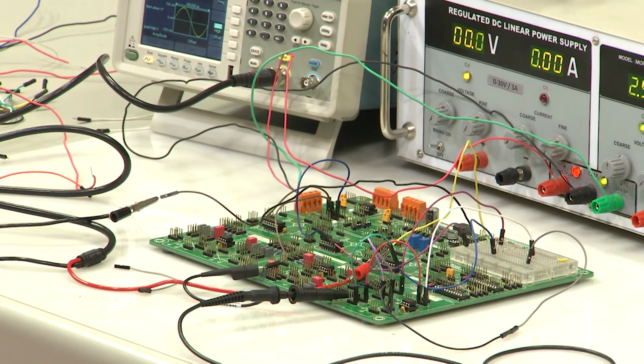As you can see, that range is very much dependent on the kind of gain that we have provided for the circuit. So, today in this experiment, we have connected an op amp in its inverting configuration, and we have given a gain of roughly 2.2. The gain is constructed by resistor combinations. The gain of an inverting op amp is given by minus R2 by R1, where R2 is the feedback resistor from the output to the input, the input here being the negative terminal of the op amp, and R1 is the input resistance, after which we give the input. So the formula for the gain is minus R2 by R1.